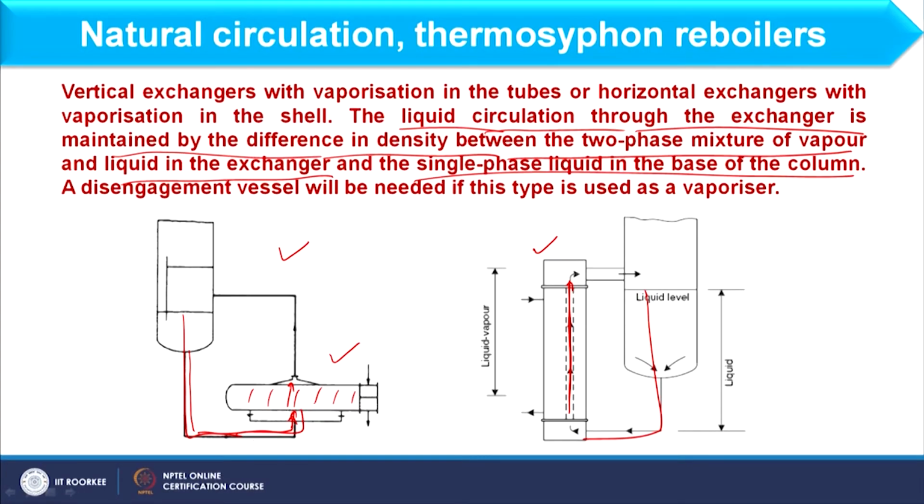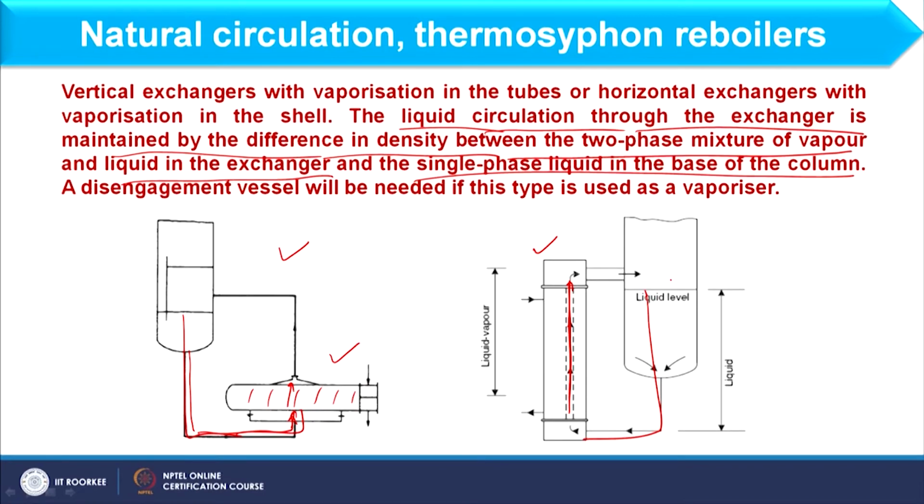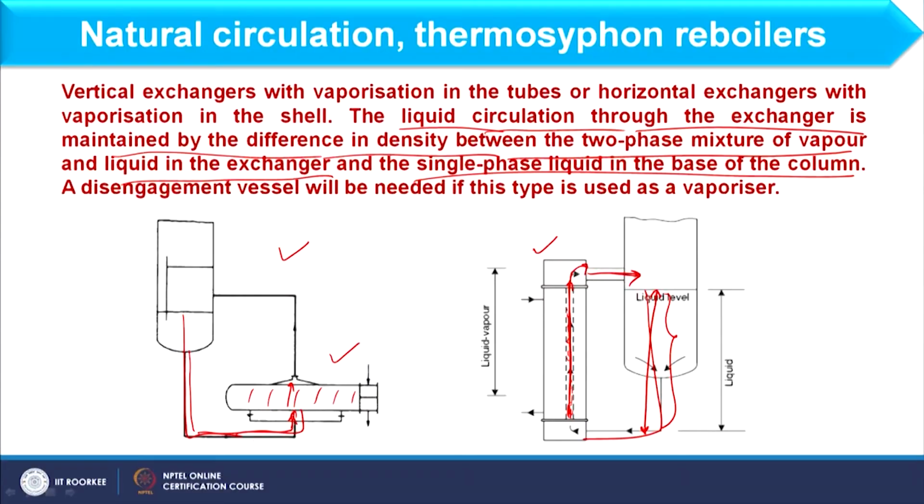So, how do we make the natural circulation? If I consider this schematic, whatever pressure drop is available to us is available from this height to this height. When liquid enters here, it starts converting into vapor, and the vapor liquid mixture moves up and then enters the distillation column. In this way vapor continuously forms and moves upward because of the density difference. That vapor also includes a certain amount of liquid which also moves upward, because continuous feed is entering from the bottom.